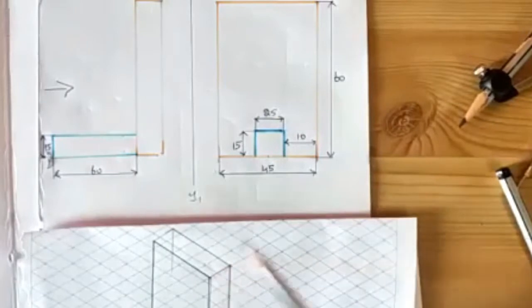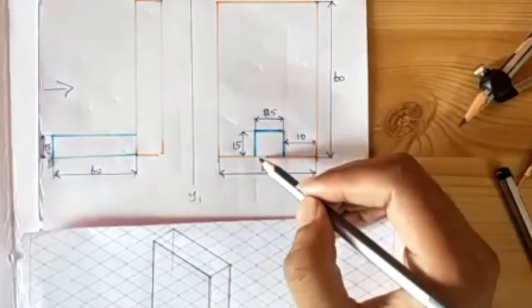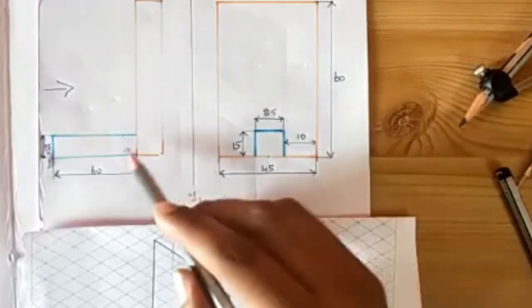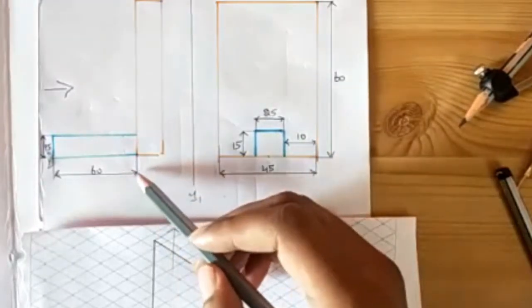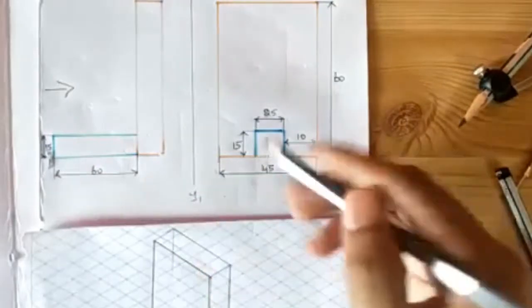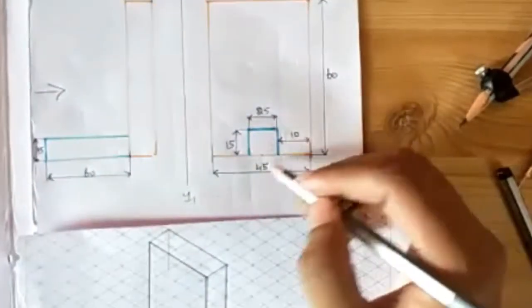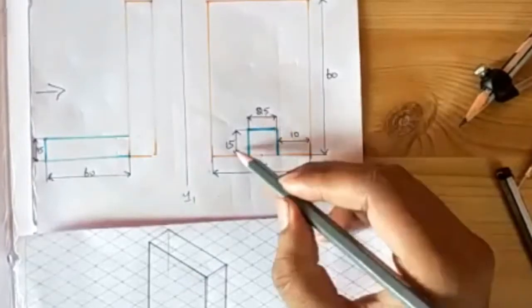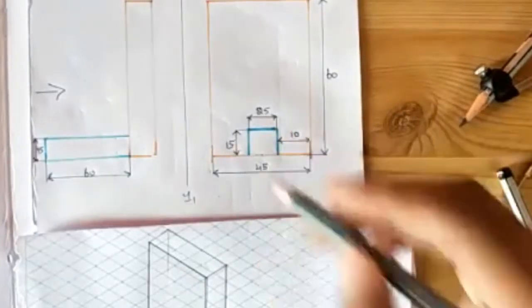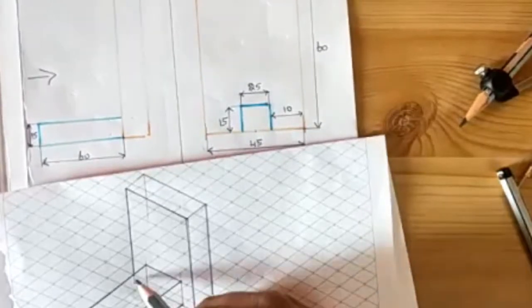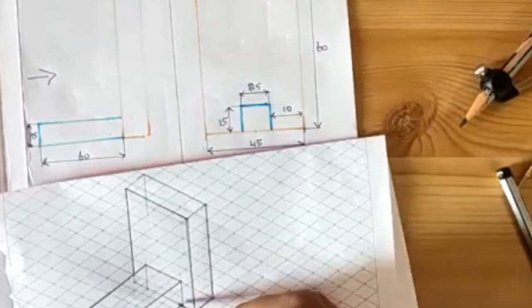Fine. Then after drawing this, at the bottom, in the middle portion of the rectangular prism, we have another projection of a rectangular prism. The total length of the rectangular prism is 60, but when you look from the side, you can see the thickness of that. It is 25 into 15. What I have done is, from this point, I left 10 boxes. Again, from the other corner, I left 10 boxes. Finally, we will be remaining with 25.